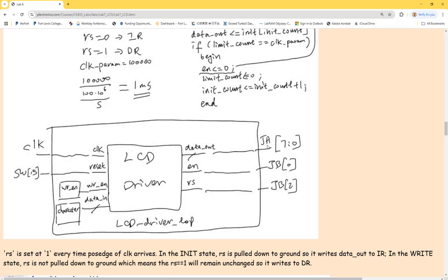These are just general purpose IOs. All the other IOs are already shorted to some of the peripherals, including the LCDs, LEDs and 7-segment displays. These ones are made available for the customer, so they are not shorted to anything else. They are just GPIOs. So for JA and JB, go to the constraint file and uncomment all of them. And for the hardware, directly short.